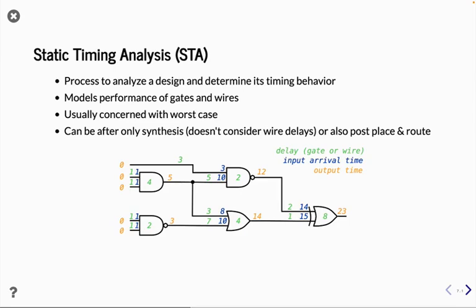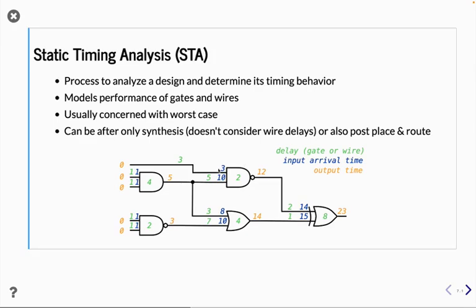The reason we use the word static timing analysis is that we're doing this agnostic to the inputs, just looking at the circuit in general. You can imagine doing a dynamic timing analysis where you're doing detailed simulations and seeing how certain transitions from 0 to 1, 1 to 0 impact certain things. Also okay, but usually STA is sufficient now that STA is so well done. And we're concerned with the worst case. So STA is going to say, given the worst case delay for this logic gate and the worst case delay for this other logic gate, what's the worst case delay for this toggling?